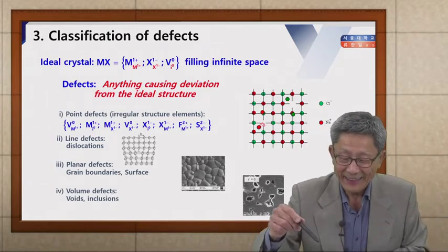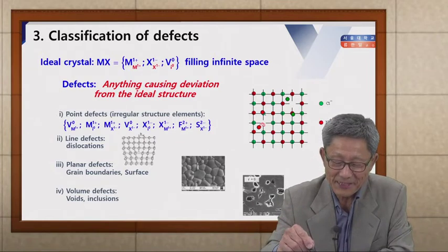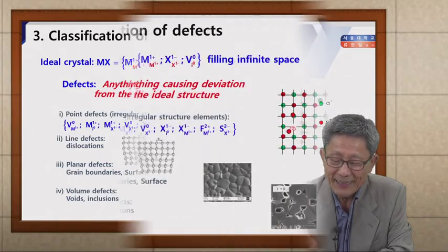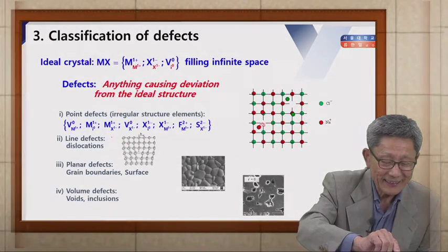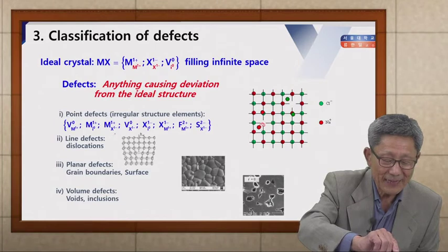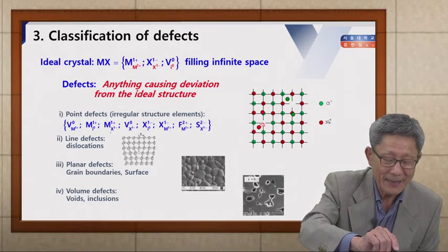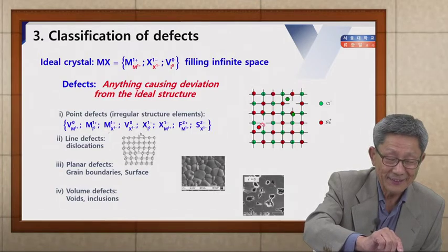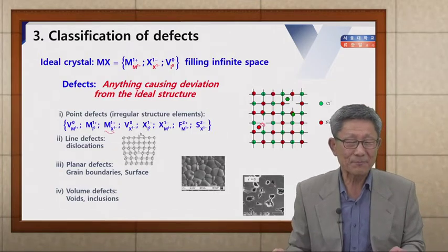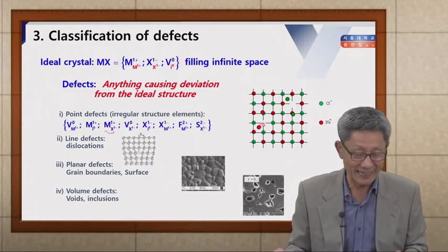And then the third one on the cation sublattice. You see this cation? Actually, this site was originally occupied by an anion, but a cation may replace this anion. The anion site should be taken by a -1 charge, but there you put the monovalent cation. So we call it the misplaced defect, a misplaced ion.